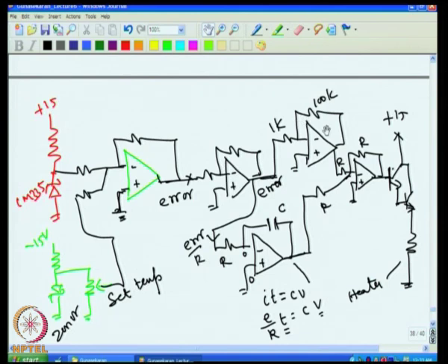So, normally what is done is we keep about 50% margin. If we need a gain of 100, we keep a gain of 50 as proportional action, and then the system will not oscillate. Then we add the integral time constant. Since the gain is less, if proportional action alone was there, you would have got a lot of error. Because of integral action, now the error also goes off and the system stabilizes without any oscillation. So, the gain should be set correctly like that.